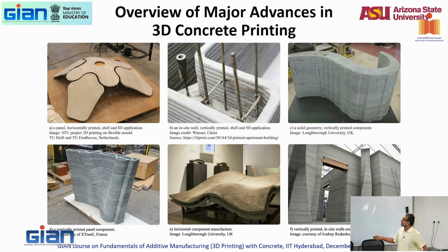This is how we reinforce 3D printed concrete, right? So in the house that we built in Tempe, the concrete wall, they said we have to have 4,000 psi, but the double-wall was not supposed to be carrying any load. Every 10 feet you had to put in a column, physically put in rebar and grout it so that these are all columns. And then the walls are simply there. It'll take a lot of load.